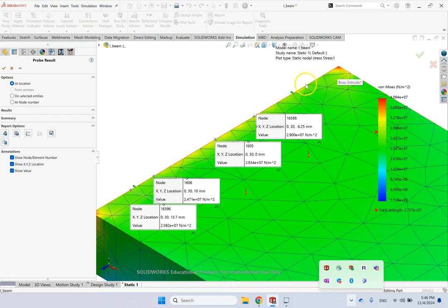You see? So in this region, I should expect about 20 something. This is my maximum stress, 20 something. And in that region where it's very, very high, an outlier, it jumps. That is not the actual stress that I should be reporting.